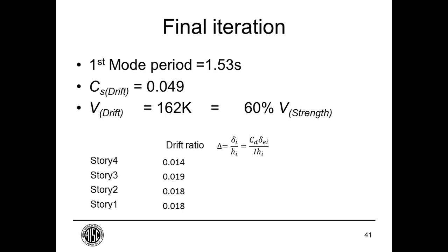So we could have gone up to 2.5%, but because this is a building with cladding, going out to 2.5% means that the cladding has to be detailed to accommodate that drift and still perform without life safety hazard. So we've arbitrarily limited it to 2% in order to permit a more economical design of the total building rather than just going out to the maximum drift limit.